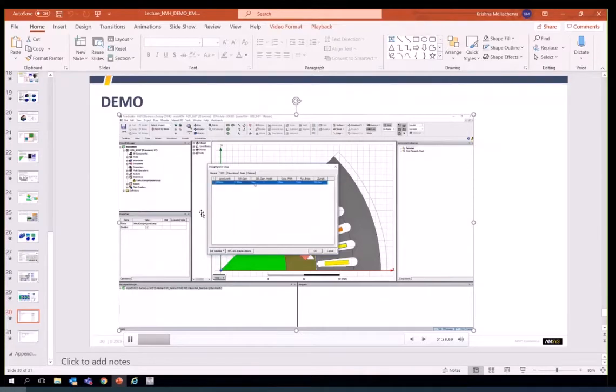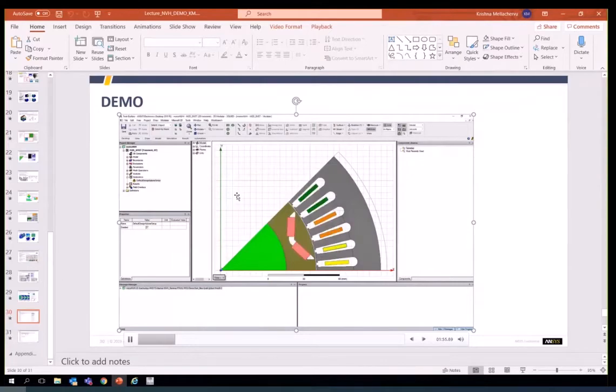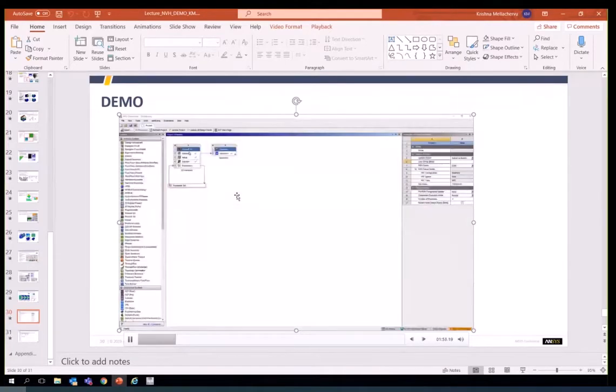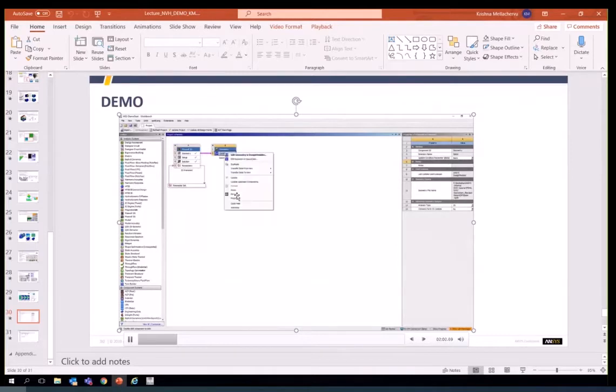We can also run it for multiple RPMs. So we can do it for 1 RPM, especially for making these waterfall plots. We have to run the simulations for multiple RPMs of the motor. So here is where we can also add RPMs on the Maxwell side, and in Mechanical is where we'll also see how we can add more RPMs there.